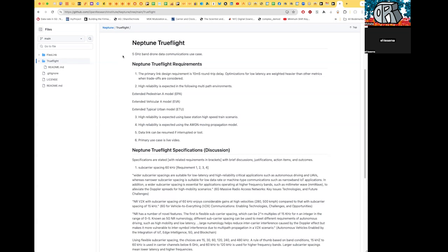We're well down that path with 2 articles, one about Zadoff-Chu sequences that are used in our preamble, and another one on space frequency block coding, which is a way of adding resiliency to the signal. So since we've already put some time and energy into that, I think it would be good to at least defend our choice on OFDM and to explore other modulations that we may have overlooked when we started down this path of Neptune.